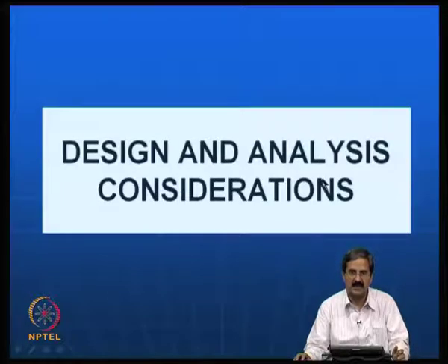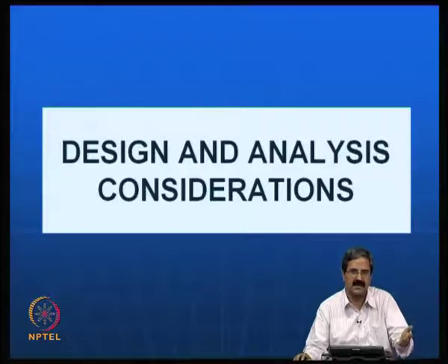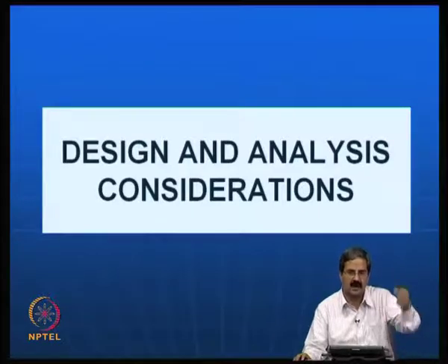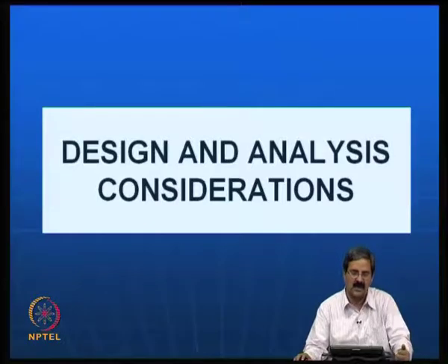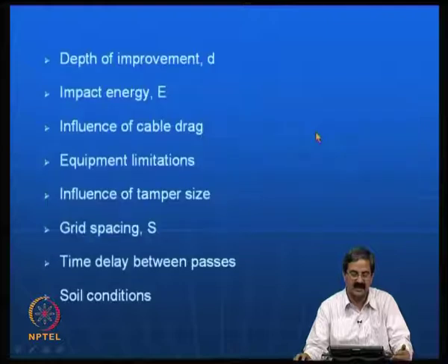Then how do you go about design? One should understand that this is a technique that has been very effective, and people have used it in some places. They have understood that dynamic compaction helps, and they are trying to analyze it, because the advantage of analysis is that you can design properly. In the design you can get the depth of improvement, and know what type of energy you can give as an impact.